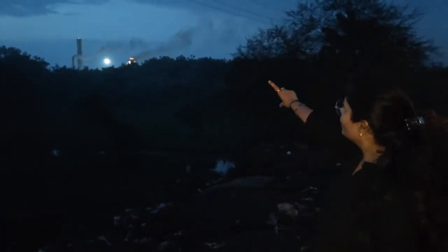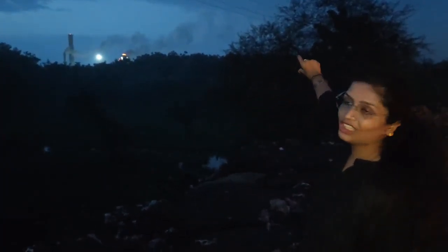It is a Coning Plume, and I guess you guys know that a Coning Plume is formed when ELR is less than ALR, that is, the environmental lapse rate is less than the adiabatic lapse rate. So just check it out that due to the effect of wind velocity, here you can see a cone-like formation of the gas which is being emitted. Now let's go to the studio and study in detail about Coning Plume.